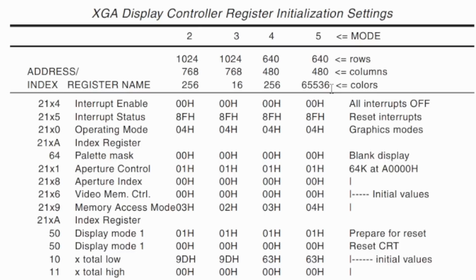And so that information was just taken directly from video RAM and sent straight out to the digital to analog converter. But there's a disadvantage with this mode. You can't use it with the coprocessor, so you can't do any of the drawing functions in 16-bit color. So that's really a shame. It would be nice to have 65,536 colors and a coprocessor. But fortunately, if the tables in that other book are correct, our chip actually does that.